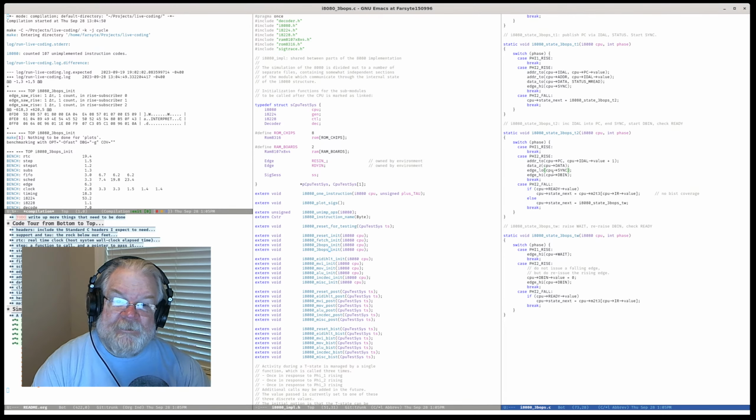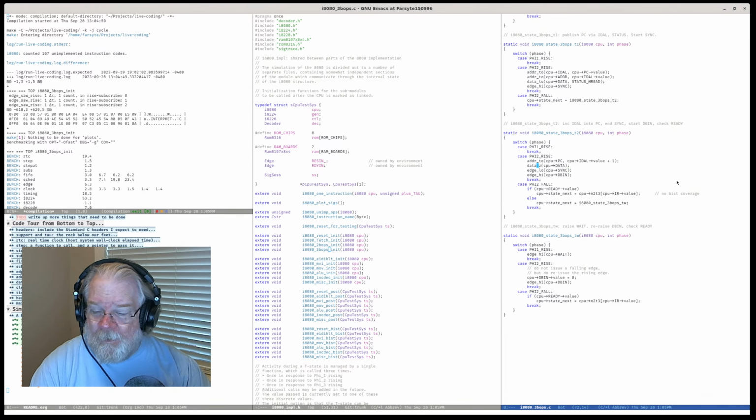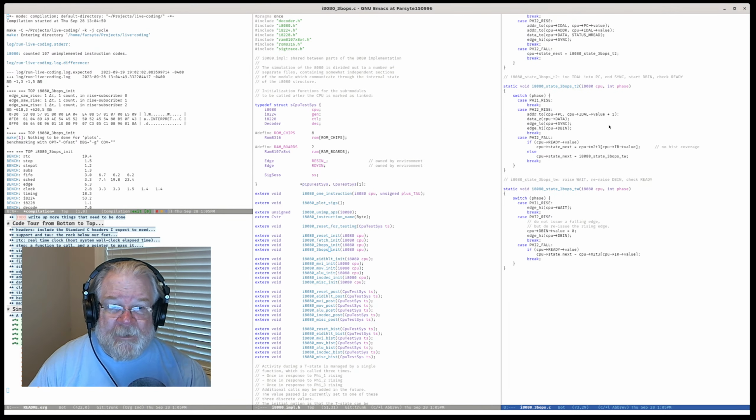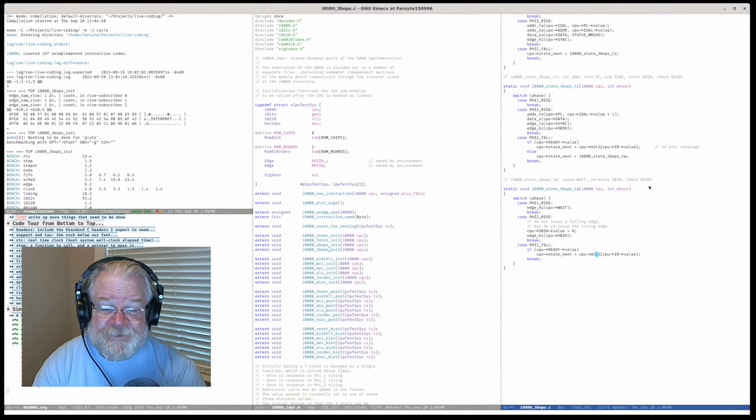But data Z, there are no edge-triggered effects at data Z other than what we're using to do signal tracing, so that shouldn't matter. So we switch from outputting sync to accepting our data in. And then we either wait or M2 T3. This is wrong. This is M3 T3. This is why I go over these things carefully.